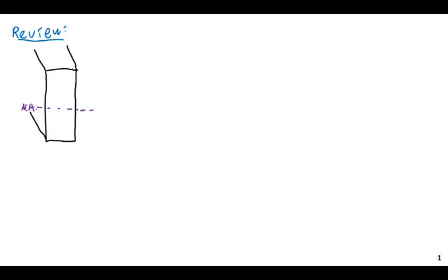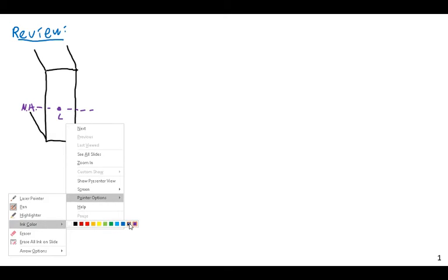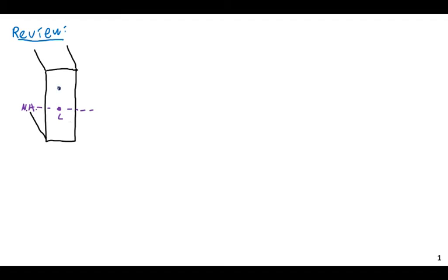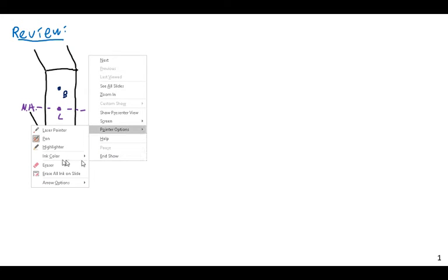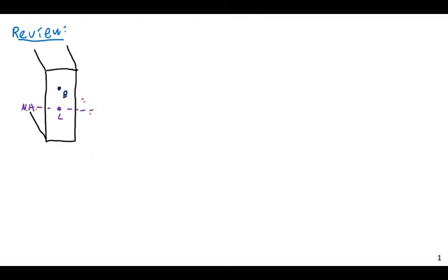Then I'm going to look at a point C here. Then I'm going to have a location somewhere in the middle that I'm going to call point B. So this could be anywhere along the height. And then finally I'm going to have a location that I'm going to call point A, which would be located at the outermost fiber, at the top or the bottom of the beam.